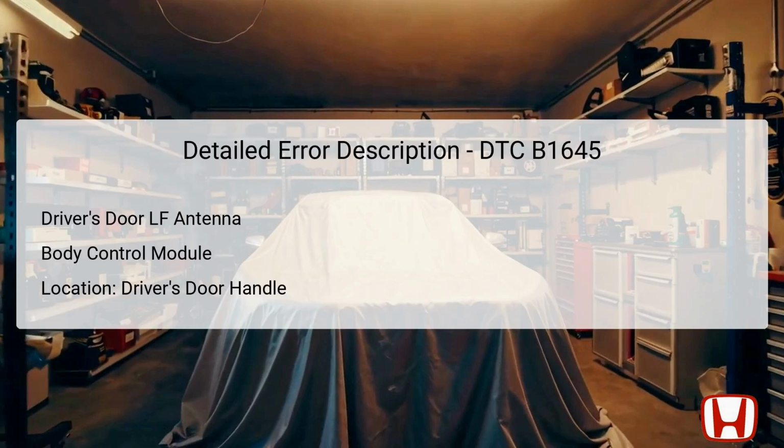The driver's door LF antenna and body control module are key components involved in the DTC B1645 error. The driver's door LF antenna is primarily integrated with the driver's door handle, playing a crucial role in keyless entry functionalities and other electronic access systems. The body control module, BCM, manages signals received from various inputs, including those from the LF antenna. When the BCM detects a fault in the antenna circuit, it indicates that there's a short or an anomaly that prevents the proper functioning of the antenna.